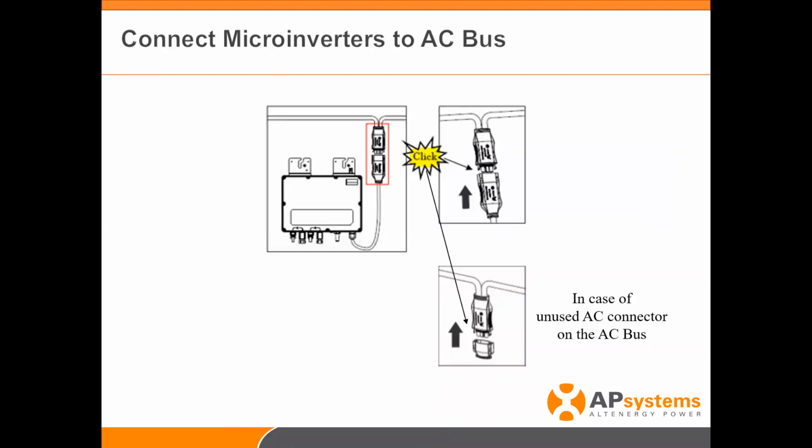As far as connecting the microinverters to the AC bus cables, super simple again. I mentioned earlier it was a poka-yoke connection. So basically it means they can only go together in one orientation. You cannot put it together wrong. There's 2 little tabs on either side of the device, so you'll hear a double click, click, click, when you're putting this together. You can feel it, but you also have an audible click to know that you've made that AC connection properly on the roof.